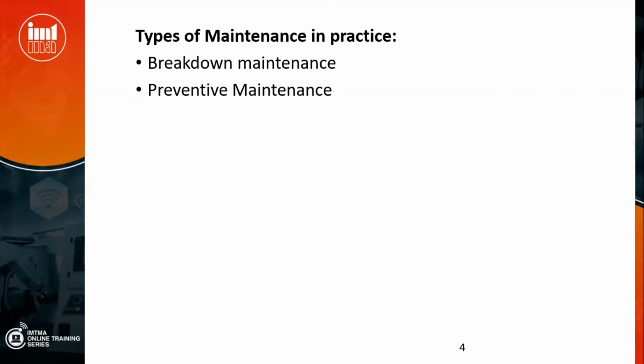If it is pressure, what is the pressure? What is the temperature? What is the noise level? What is the vibration level? Wherever you can quantify the results and readings, you must put them that way. Just tick marking will not serve the purpose. So also you must compare after preventive maintenance. It applies to every type of maintenance, whether mechanical or electrical or any type of maintenance. The concepts apply to all types of maintenance.